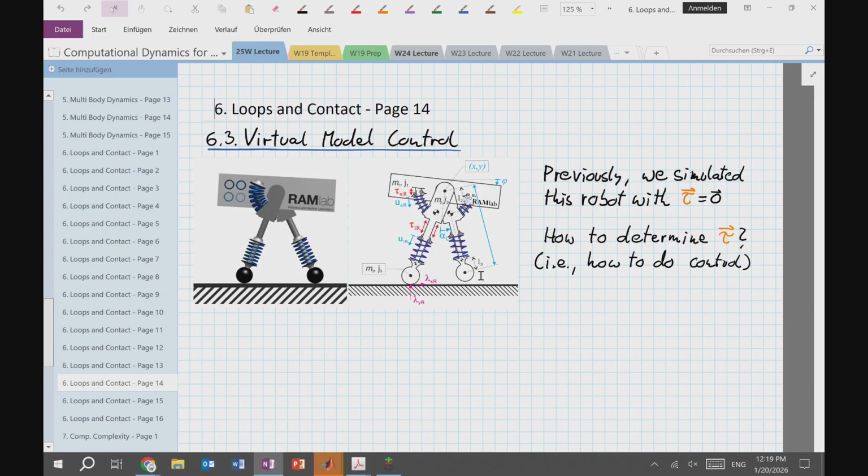Of course, if you have low PD gains, your robot is going to be a little bit the lazy bot, hanging out there, because you have gravity and other things. And with PD control, you have steady state error. So we do feed forward, so we do gravity compensation. Then you can be soft, but you still have no steady state error, right?